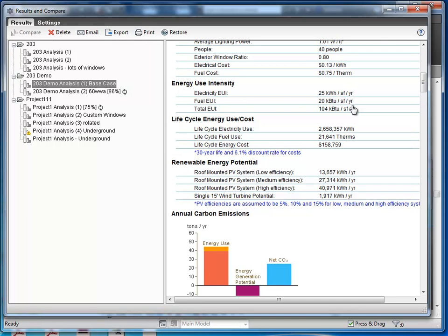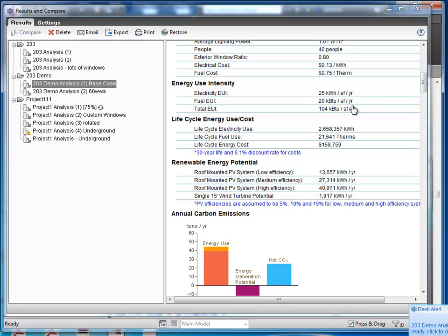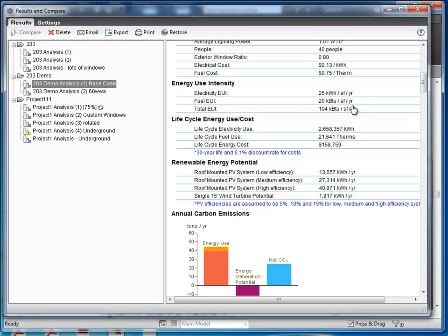The other thing Scott Davis was mentioning is that if it's sloped, for example, and so it's like ground on one side and not ground on the other side, you can create a separate mass and not enable the energy model for that, and that should work as that thermal mass. Again, I think that's something that's a little bit more complicated, and so if you're doing that, then just come talk to me and I'll help you.